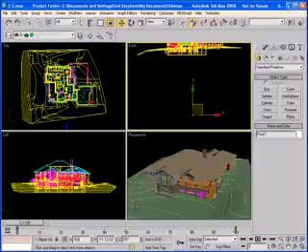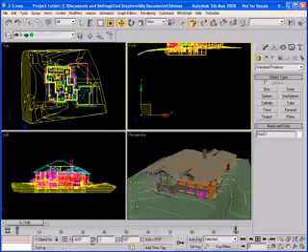I'm going to add an X coordinate here. Let me try about a minus 82 feet. Going to bring it over in the X direction. In the Y direction, let me go about a negative 3 foot 6 inches. And my z-axis, this will probably be off. I'll probably have to manually move it, but let me try. I'm going to go minus 3 foot 6 inches there also for the height. And yeah, so the height is still off, so I'm just going to manually move it into position.